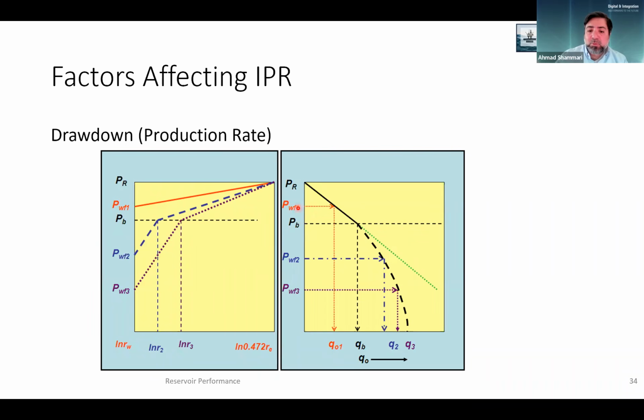And why do we have the flow bottom pressure above the bubble point? Well, because the drawdown is not very high, and hence it is a straight line. However, as you produce more at higher rate, you will find more drawdown, correct? And hence the fluid will reach the bubble point pressure, and then we will see that there will be more pressure drop after the bubble point. Why? Because we have two phases now.